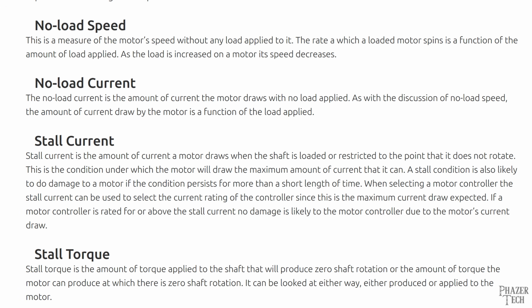Now, really quickly, a few other specs you should be aware of are the stall current, no-load current, and starting current. Let's say you connect a motor to a load that's too heavy for that particular motor and it gets stuck, or in other words, it stalls. The stall current tells you how much current the motor will consume when this situation occurs. And again, you'll want to make sure that your power supply and driver are capable of delivering this.